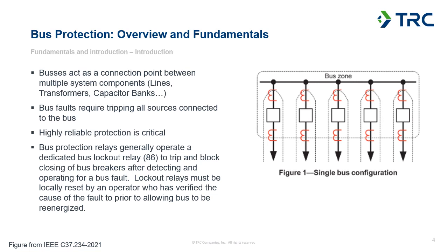So once we select our protection, generally what we're going to do is we're going to set that bus protection up to operate a lockout relay. And lockout relays are either physical switches that are electrically operated, or can be implemented logically within the relay logic as well. But those are designed so when the trip happens, it will both provide a tripping function for the appropriate breakers, so to clear all of the breakers on the bus.